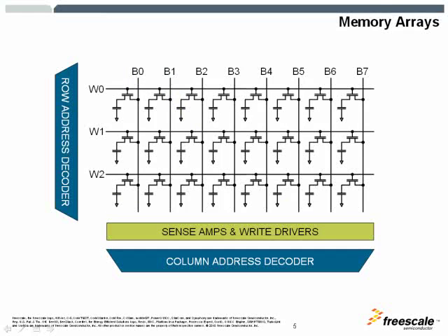So a single memory cell is not sufficient. They are organized in row and column fashion, as you can see. It's a two-dimensional array. The address that is going to locate the memory location is sectioned in two parts. It's decoded into rows and columns.